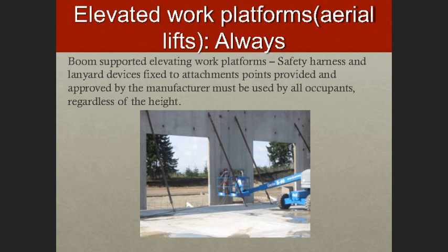And again, this is my own recommendation. Call me if we need to discuss it more, but in certain situations it makes more sense to wear a shock absorbing lanyard, especially if you're working at great heights with these aerial work platforms. And in other cases it makes sense to just wear an ordinary lanyard that does not have shock absorbing properties to it. So that can get tricky, so if you want to talk about that more, please let me know.